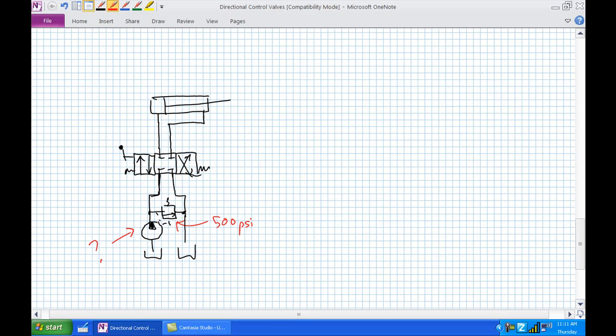But what's this pump constantly activating at? It's at 500 psi. That's a closed center position. And it's not the most efficient means because it's constantly trying to force against 500 psi. What if I did the following tiny modification?